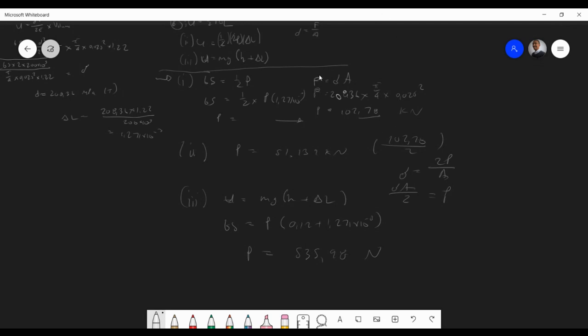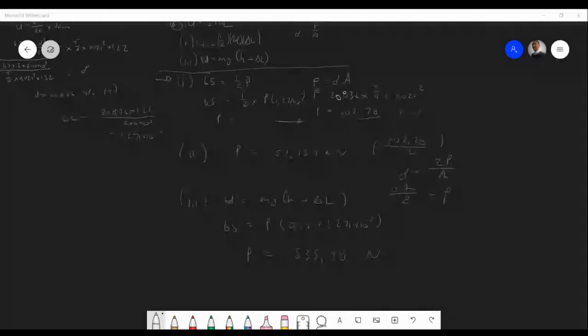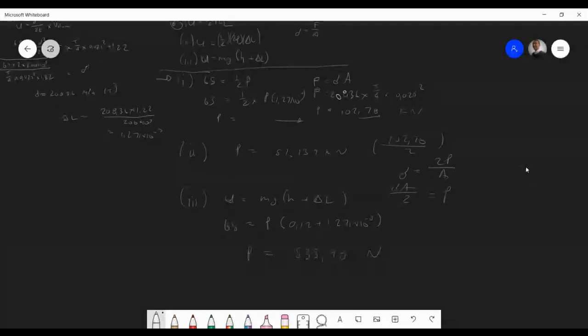And when you gradually apply a load to induce an energy of 65 joules, you require a big amount of force, applied over a steady or constant period of time. So the point here is, even though you have a smaller load, if it's coming on an impact, you can still get the 65 joules.